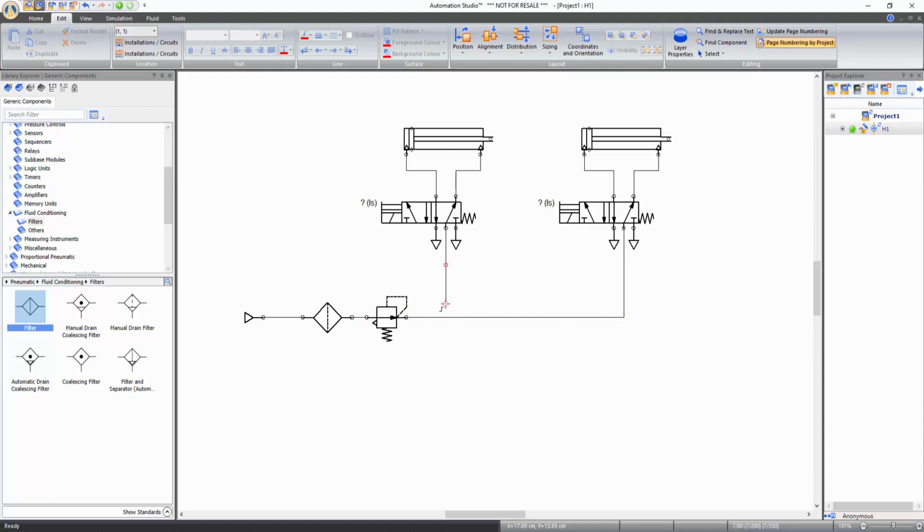While tracing a line coming across another line, there is no target sign that usually allows you to make a connection. Therefore, you need to double-click on the line to make a junction. When a 3-line junction is created, a filled black connector is automatically created at the junction.